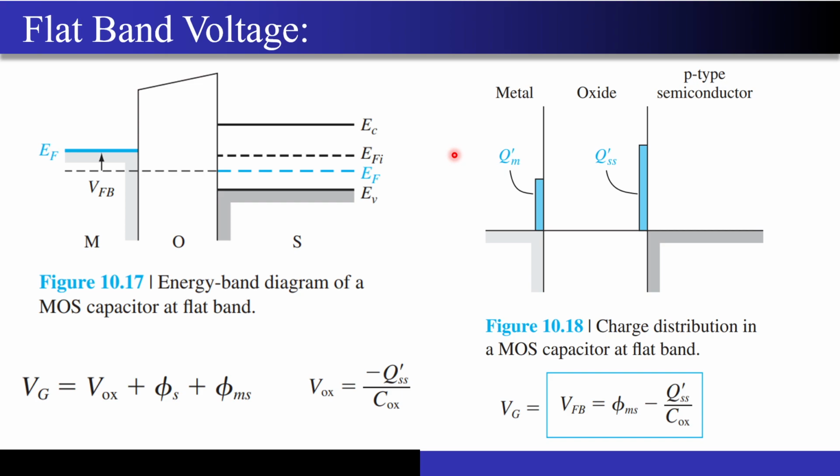So the amount of effort that I need to create the inversion layer at the Si-SiO2 interface, if these positive charge impurities are present, will become less actually. And that is why you can see we have a negative sign over here, because your threshold voltage actually decreases when you have positive impurities present in the oxide, right? So that's why you have a negative sign present over here.